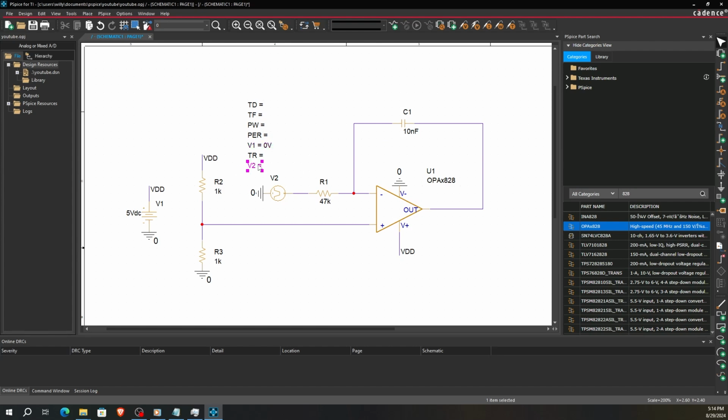The pulse source is basically how you can make a square wave. Make V1 0 volts and V2 5 volts. Leave TD blank, since it's simply a delay before the signal starts. TR and TF are your rise and fall times. Set them both to 1 microsecond.